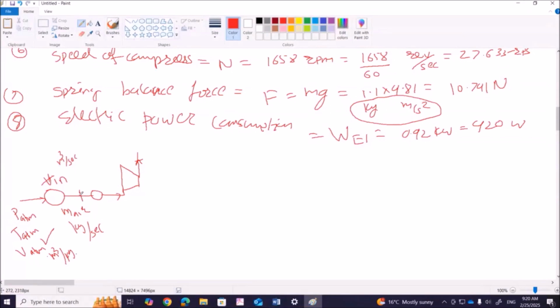So now here, the air, this is an atmospheric state. So now this is number one state. I will get here P1 and T1. So I know pressure, I know temperature. I can find out a V1, no need now once I know mass flow rate. Now this air goes in a compressor where the pressure is increased to P2 and T2 and V2 specific volume.